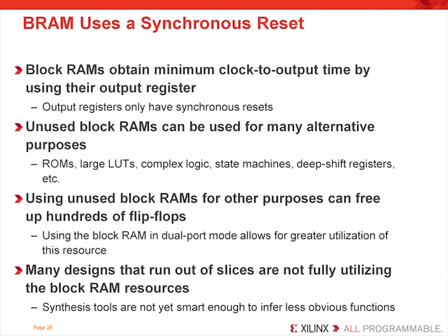Likewise, many customers try to infer the block RAM resources and are disappointed when their synthesis tool does not allow them to build what they want. Well, this is a typical limitation of most synthesis tools, including XST. One of the benefits of using the block RAM is that it has a minimum clock-to-output time when the output register is used. But what designers don't realize is that, like the DSP slice, the block RAM does not allow inference of an asynchronous reset, which of course has bad coding implications if you build with an asynchronous reset. This is because there is simply, again, no asynchronous reset functionality built into the dedicated block RAM resources. So to infer the block RAM's output register functionality, make sure you use a synchronous reset.